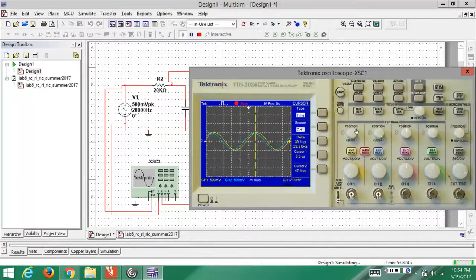You can either use the peak of the waveforms to measure the difference, or you can measure from the point where they intersect with the x-axis, whichever is easier to locate. I place it on, yeah. If you look at the cursor now, it is right on the waveform where it intersects the x-axis, and take the reading for that time.